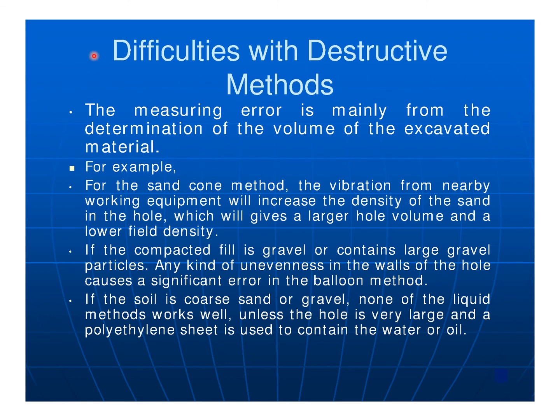Okay, difficulties with destructive methods. The measuring error is mainly from the determination of the volume of the excavated material. For example, for the sand cone method, the vibration from nearby working equipment will increase the density of the sand in the hole, which will give a larger hole volume and a lower field density.